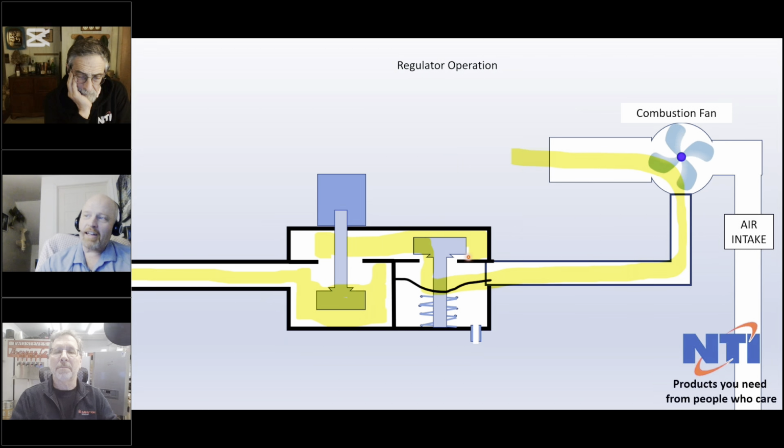It's not bad, but it's not perfect. Okay. So you would recognize this as being an old car guy. If you took your car up to Colorado, you'd have to retune your carburetor. Absolutely. You'll notice the gas valve has effectively no electronic components. It's got a solenoid that's on or off, so it's open closed. Everything else is done with springs and diaphragms. So while it has the effect of compensating for changes in air pressure, it's not a perfect compensation.